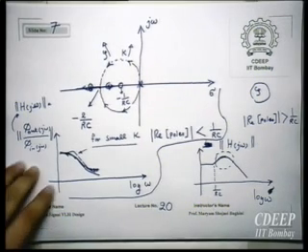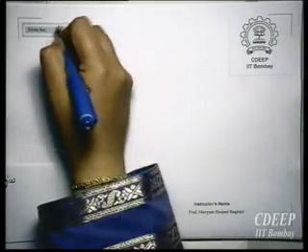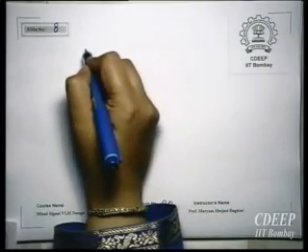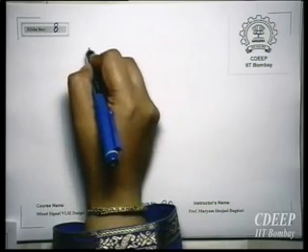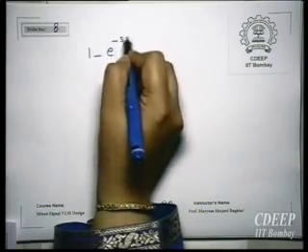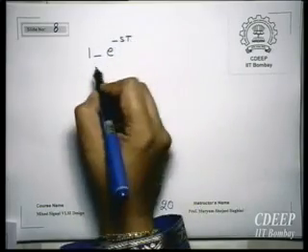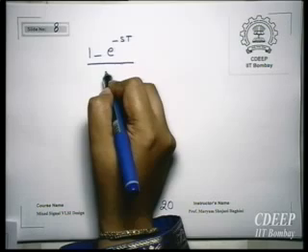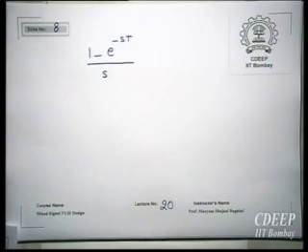Because see, this is very interesting because this charge pump is a discrete system, right? As I showed you last time, what was the transfer function? 1 minus e to the power minus sT, upon s, right? T is the sampling cycle. This was the coefficient of that sampling.